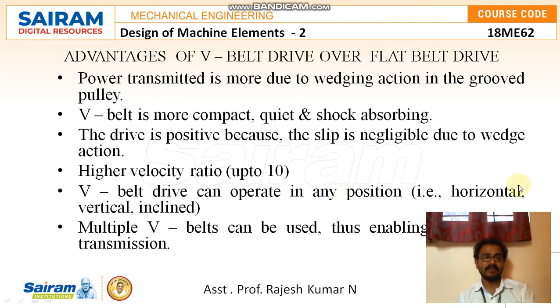And moving to the next one, advantages of the V belt drive over the flat belt drive. So this is again a very important concept, because from an examination point of view this question is important. The first point is that the power transmitted is more due to the wedging action in the grooved pulley. Because in the case of the flat belt, this kind of wedging action is not possible because it is flat and the thickness is uniform. But since the V belt has a wedge shape, the power transmission here is more.